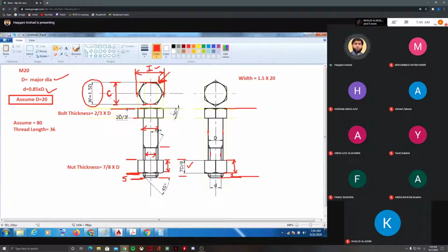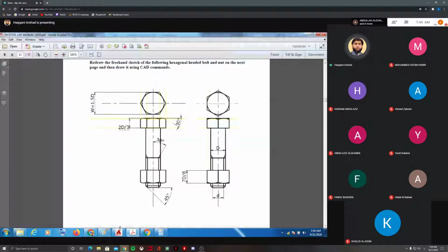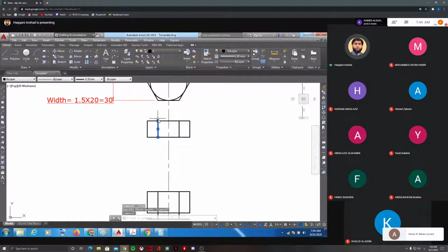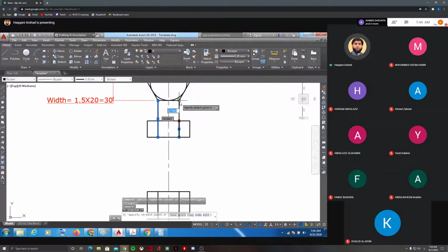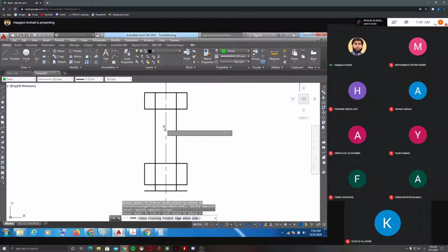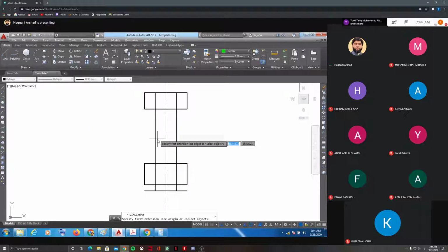Now there is usually a common mistake done by the students. What they assume, when you see these lines in the drawing, this line is a projection from the hexagon. Actually, these lines are a projection from the hexagon only for the arcs. What the students generally do is they think that this is the capital D. They just project it or forget to delete the lines, and they think that this is D, but this is not D. You see the dimension from here to here.